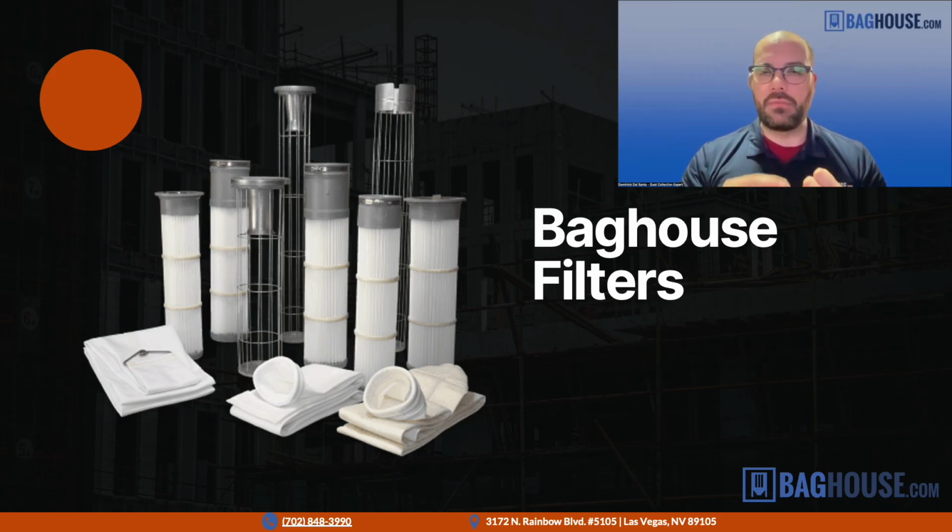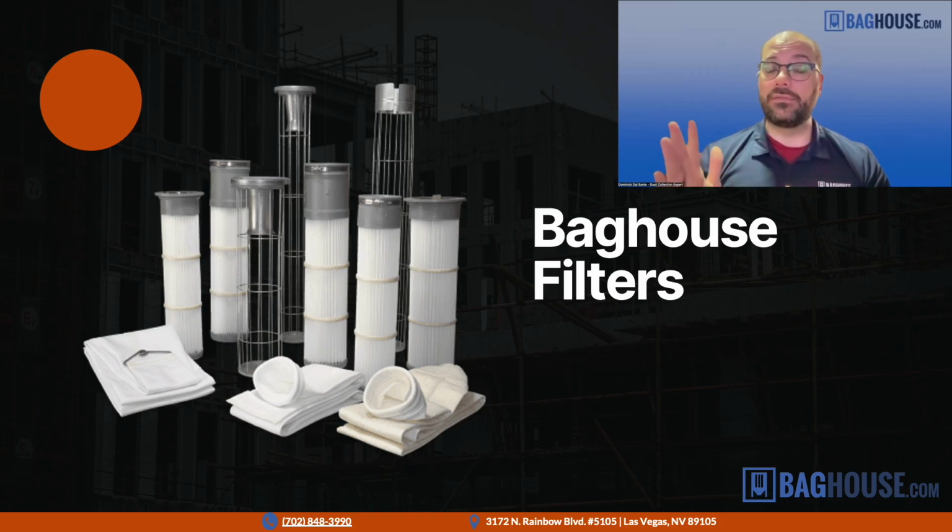And then in many cases, where we need to collect a higher percentage of the absolute smallest particles, or if the material we're collecting, for example, is extremely toxic, highly regulated, whatever it might be, then we might apply on top what's called a PTFE membrane. This is different from PTFE filters, where the bag is made out of the PTFE.